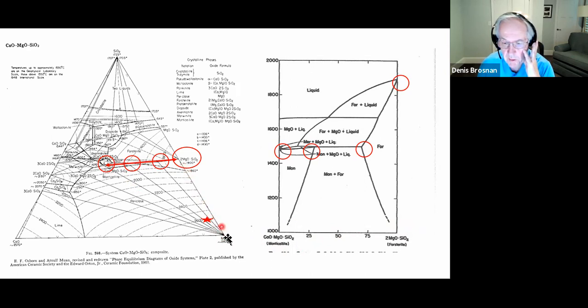We're going to look at the MgO, forsterite, monticellite compatibility triangle, but it's really composed of 1, 2, 3 little compatibility triangles. And the reason these are drawn here is there are different points here where liquid can form.